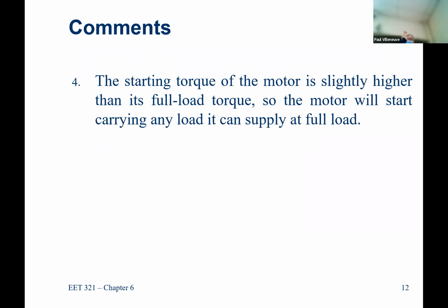So remember, you only are controlling the shaft. You only have output on the shaft. That's 1 inch. What if the fan blade is 3 feet in diameter? And you only have the capability to apply torque on that 1 inch diameter. Get that thing to spin. Try it sometime. Just rotate the shaft and see how hard that fan is to get up to speed. Very, very difficult. So fans are actually some of the hardest things to get up to speed and rotate because they have so much inertia. Think of all that spinning mass way out from the center of the shaft. It just takes a long time to start.